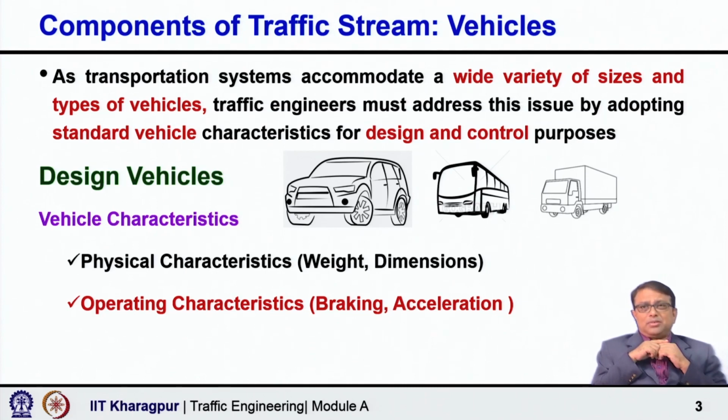Design vehicles may not be the same for all kinds of roads, because if you are talking about residential streets, we do not expect very big commercial vehicles to use those roads on a day to day basis. But if you are talking about national highways or major interurban roads, you expect bigger vehicles to use the road. So, the concept of design vehicles becomes very important. The characteristics of the design vehicle primarily govern the design of the traffic system or the road system.